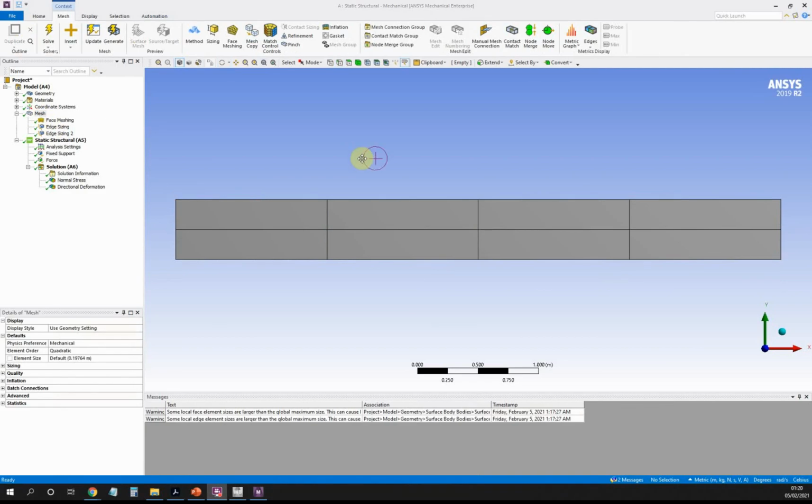So sometimes it may not be kind of clear what the number of nodes is here. So a very easy way to check this is to go up here and go to the select node. Okay, so this one here. And what that will let me do is, if I hold that down, you can see that as I move it around, it's selecting the nodes. Okay, so this one has 8 nodes. So again, you see we have the mid-side nodes in this case.